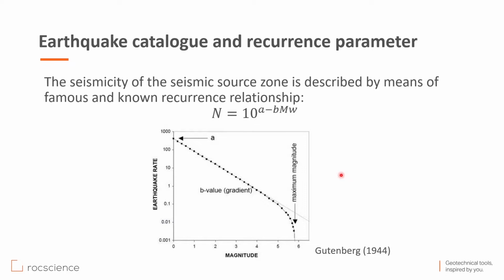Earthquake catalogs are treated in two steps mainly: the clustering of the earthquake catalog and the determination of the minimum magnitude of completeness. Clustering seismicity is the method to sort out main shocks, foreshocks, and aftershocks in the catalog and remove dependent events.